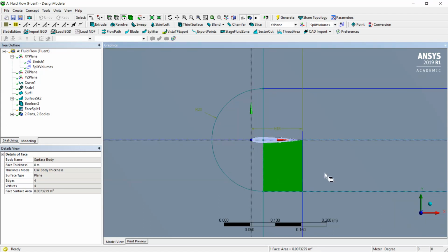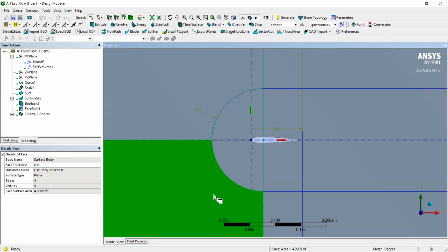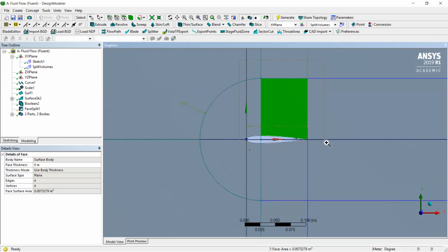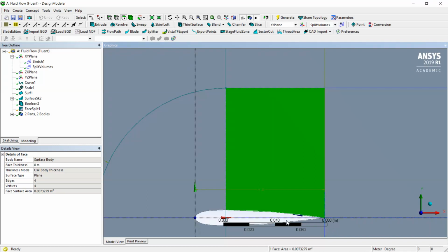So what is the strategy of the volume separation? At the end, if you are carefully looking at the geometry which we receive, every one of these volumes has 4 edges, and it has opposite edges. For example, if I take a simple geometry like this one, I zoom to it, and we will see that it has 4 edges.